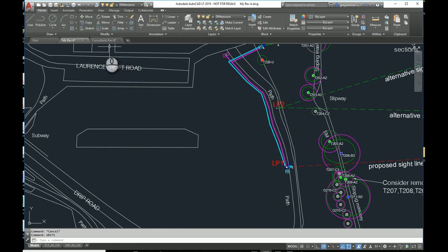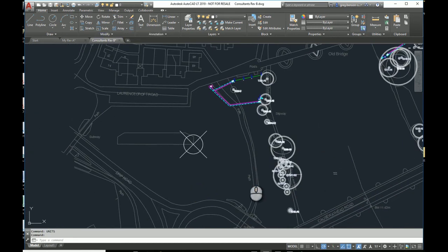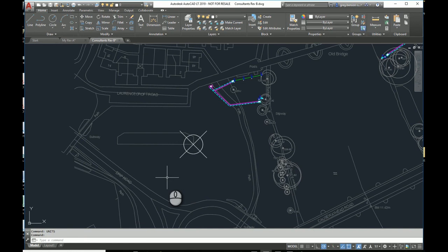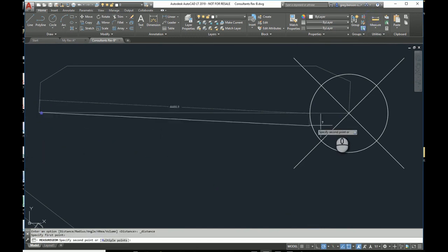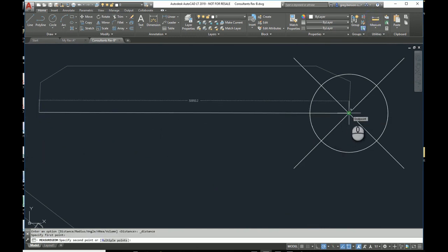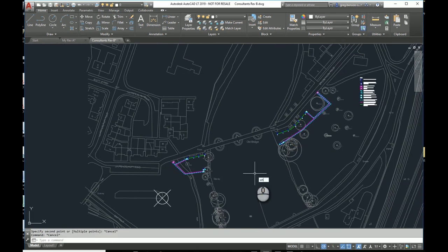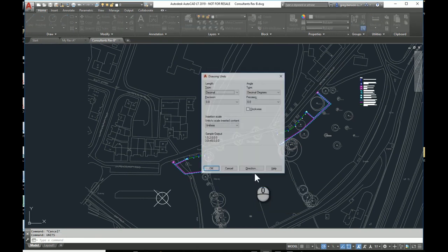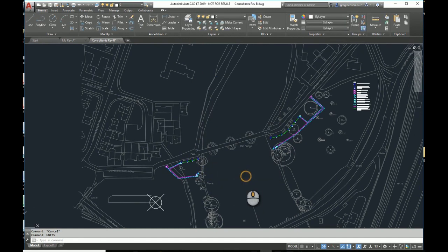Okay. We're then going to do a similar thing on the consultant's drawings, and we need to discover what was the size of this drawing, the scale of it, and when we used our measure command we discovered that for some reason this is in millimeters, but the units didn't reflect that. So all we have to do is type units and actually specify that it is being drawn in millimeters. Okay. That's step one.